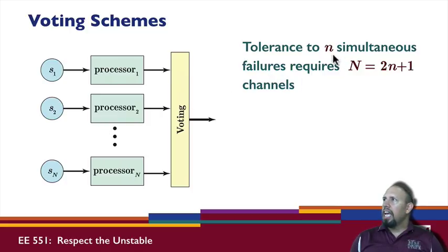If n of these fail, and they all fail in the exact same way, that leaves n plus 1 that are still functioning fine and can be used to vote out the other n. So using a simple majority vote can establish what the correct thing ought to be here. As you can see, this whole process can get really expensive depending on how expensive all these devices are, but it can be important if the thing absolutely, positively must survive.